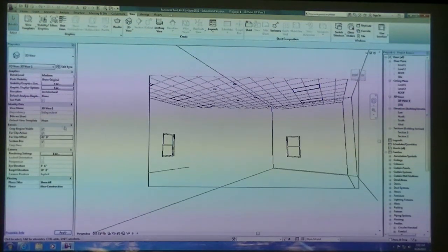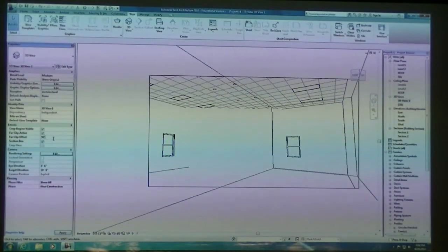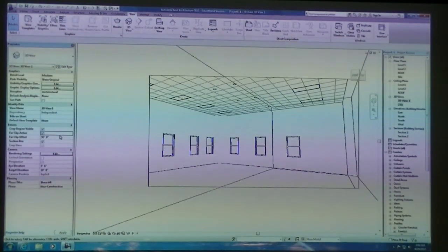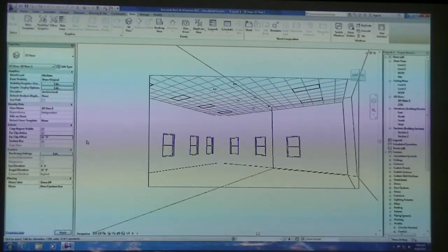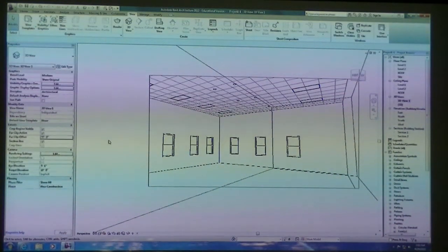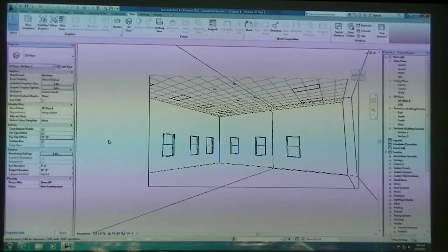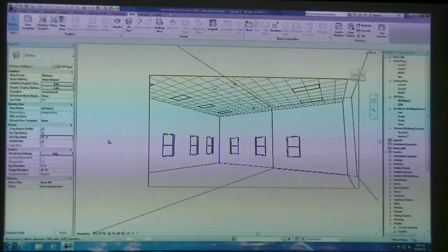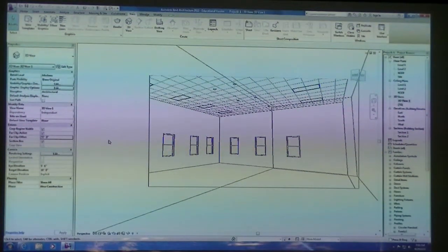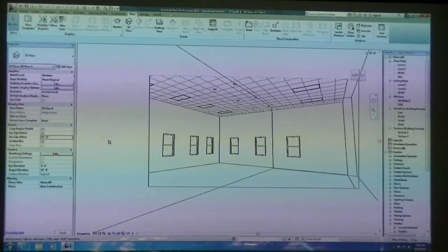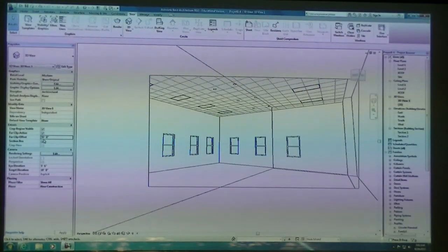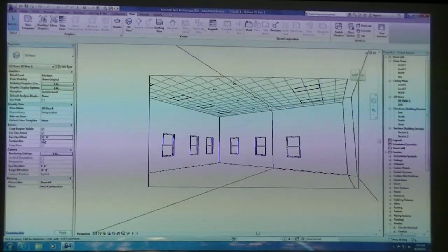Maybe my room was 76. I guess it's more like 50. Basically the far clip offset, just like in other rendering programs, stops your view once you get to the specified distance. I typed in 55 feet, and it's not going to render anything beyond that.